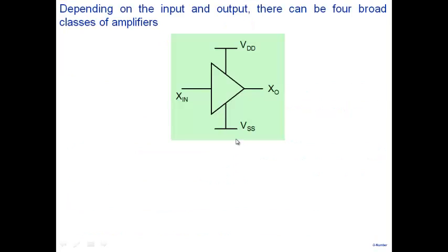All right, so first of all, before we start looking at amplifiers, there are 4 classes of amplifiers that one can have here. This is a simple picture of an amplifier that you see. We have an input here. Input is written in a general form Xn, and output here X0. Every amplifier will have power supplies here. And the way an amplifier amplifies is, it basically takes the power from the power supply and delivers it to the load here. The power that comes from the input is very small, obviously. So as we have said earlier, you can call a device an amplifier only if there's a power gain. Power gain meaning the output power divided by input power is larger than 1.